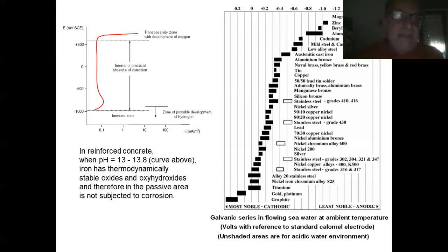Please remember that we are dealing with concrete, and the type of water with which we produce concrete makes a lot of difference. For example, the salinity, the hardness, the salt content in general terms of the water, salts of calcium, potassium, magnesium, and so on, would change, and the presence of salt, of course, would change the behavior a lot.